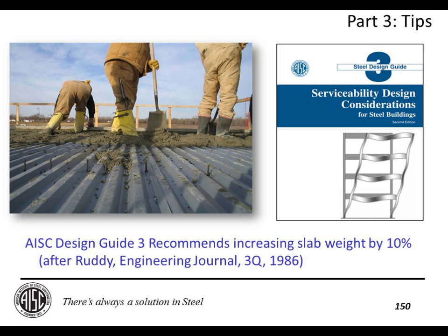AISC Design Guide 3 recommends that you increase the slab weight by 10% to handle this effect. That's something that I do in my practice. And what I've seen is really the majority of this increase is due to the deflection of the members themselves, not due to the actual deflection of the deck between the members.